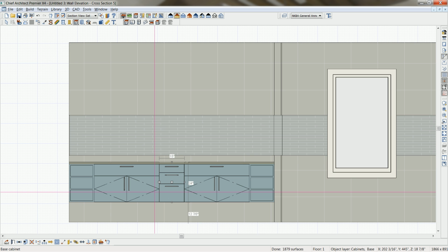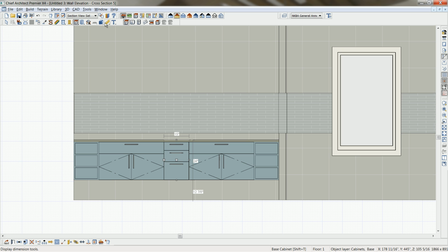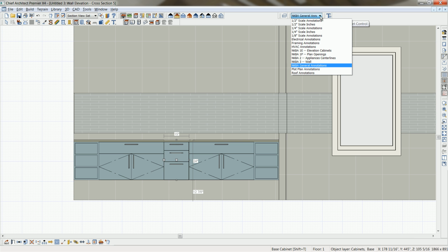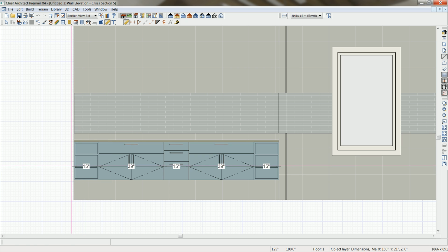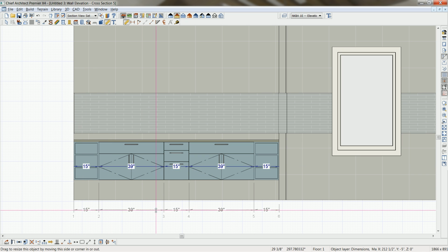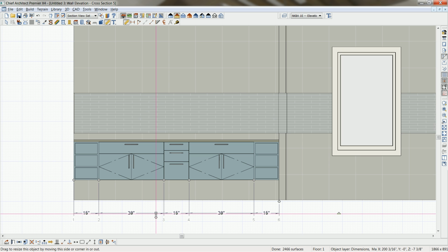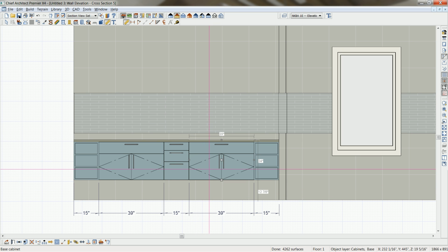So I pretty quickly laid out my cabinets here, and you saw how easy it was. Let me use my dimension tool, and let's create a couple of dimensions on our cabinets. I'm going to come in here and just pull one dimension line through here. That'll get our boxes. And then when I add my fixtures for our sinks, we'll put our centerline dimensions in. One final thing before I add the 2 sinks, I'm going to select our 2 sink-based cabinets. Got both of them selected.